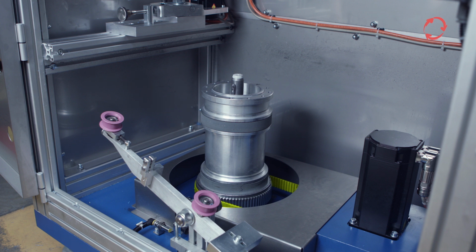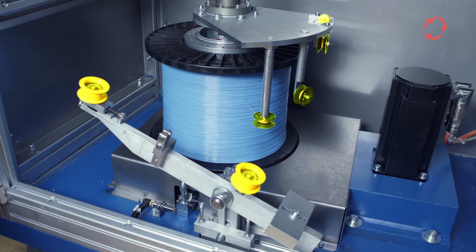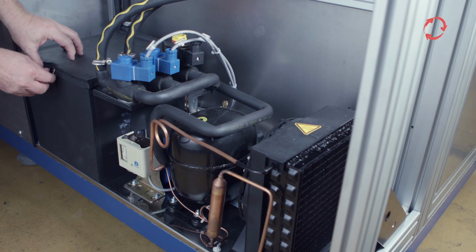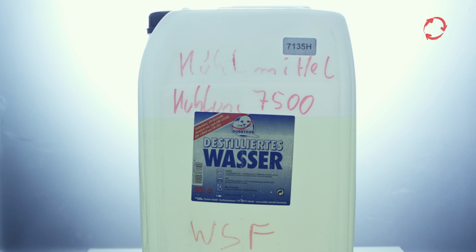In order to ensure error-free operation and machine safety, a few maintenance operations must be performed regularly. Check the drive belts and belt tension, coil clamping rings in the coil housing, winding plate, and thread guide rollers. Check the coolant level in the storage tank, and if needed, top up with water biocide mixture.